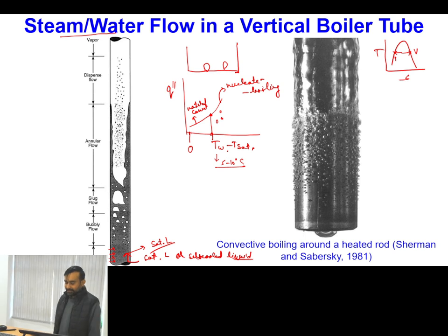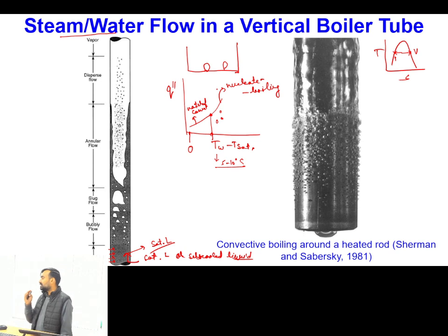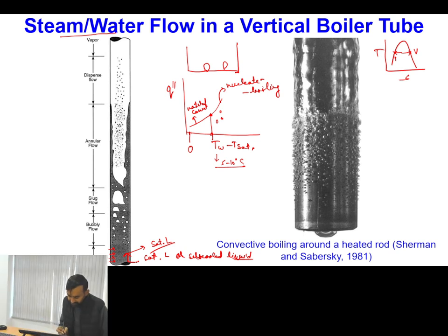But as our understanding of pool boiling heat transfer says, from the boiling curve, even if I allow the saturated liquid to flow, it will not immediately form bubbles. Bubbles will form after a slightly greater increase in temperature. So initially, when saturated liquid enters the pipe, it remains purely in the liquid phase, and we have a convection regime. After this, small bubbles form.